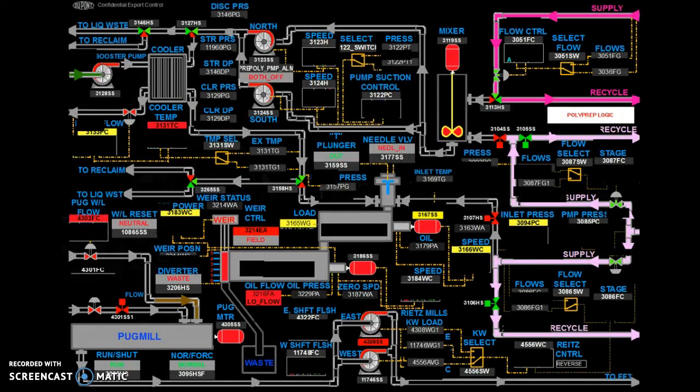When computers were first introduced to the industry to begin controlling processes remotely, HMIs were an integral part of that migration. One of their primary functions is to deliver key performance indicators to the operators, indicators such as temperatures, pressures, and flow rates. Using these indicators, operators can monitor their processes remotely and respond to any alarms that might appear. Over the years, however, a detrimental problem began to surface across the industry: the inadequate management of alarms.